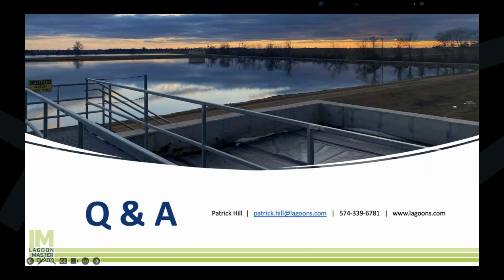And then how often should the biosolids be removed from a lagoon? Well, it depends on the rate of input into the lagoon itself. But the rule of thumb is once every 20 years, which is the Ten States conservative design standard. The reality is that because you're never actually loaded at the design loading that the Ten States standards make you design around, it ends up being once every 30 years. But it depends on the site, the rate of sludge accumulation, the weather and things like that. But if you can't remember the last time it was done, or if it was never done, I'd start looking at it.